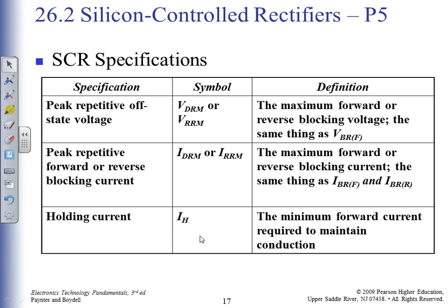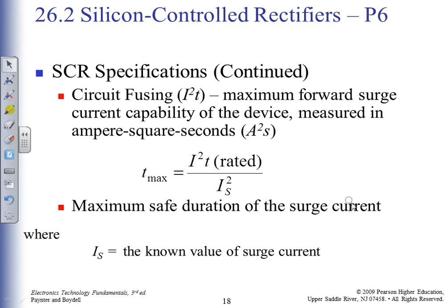Normally, a silicon-controlled rectifier is being used in an AC circuit so that when I pass through 0 on the negative half cycle of the AC wave, it turns off. So this guy's going to turn on in the first quadrant, stay on until we cross through 0, going at 180 degrees in our sine wave, and then it'll turn off for the 3rd and 4th quadrant.